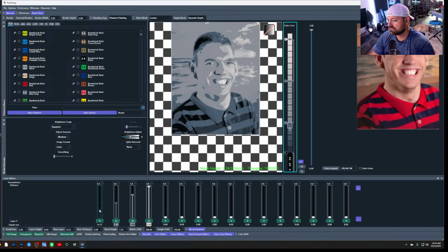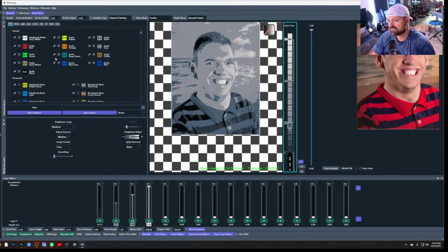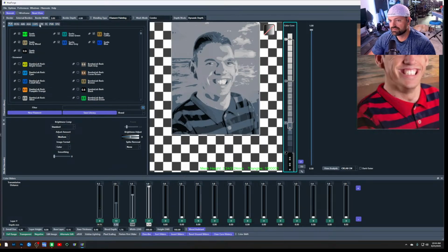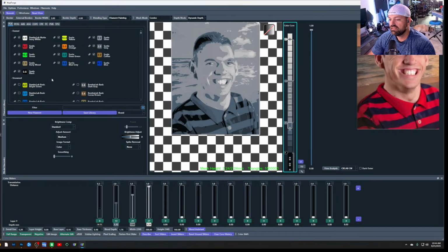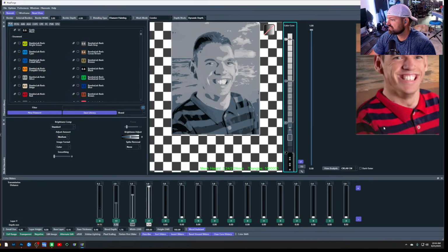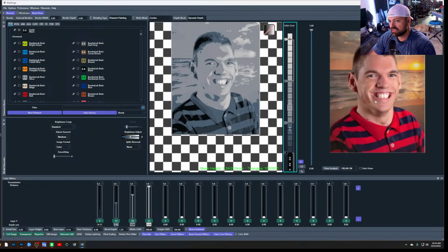So what I want to do is colorize it. Over here, this is pretty cool. These are the colors that I own. I have plenty more than this, and then it has the different colors that I don't own. You can pick PLA, PETG, whatever material you have, and then you can pick the colors too, and it's going to as closely represent the colors as it can. So there's a lot of color in this image over here, and I want to try to retain it. I have a 4-color AMS on my A1, so I can only use 4 colors.